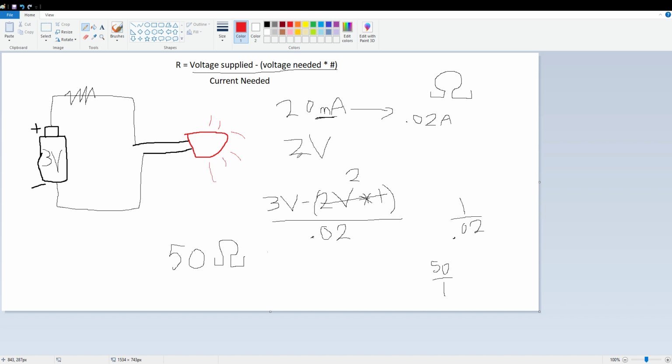The other thing is this is like the recommended current, but if you want to get a little fancy with it, you can either change this from the Arduino or with the resistors. If you give it more resistance than this, then it will get less bright, until a point where there's so much resistance that not enough current is going through it to turn it on. So it's an interesting way to dim the LEDs, to give it more resistance. And that, of course, is going to restrict some of the power going to it, which is going to make it a little duller until eventually you get to the cutoff point.